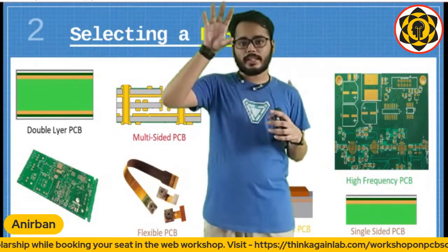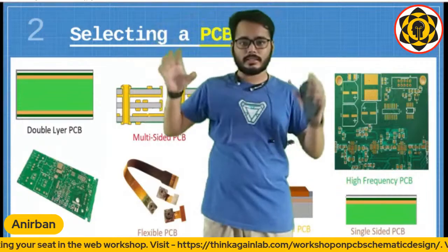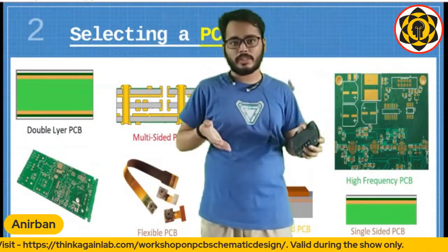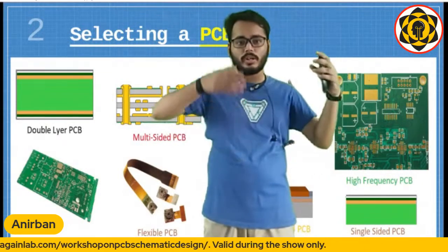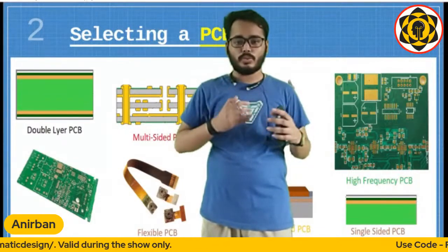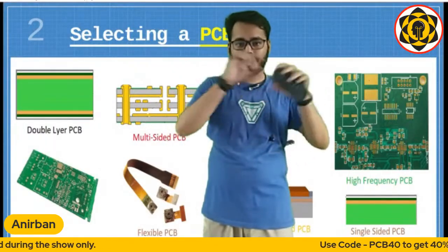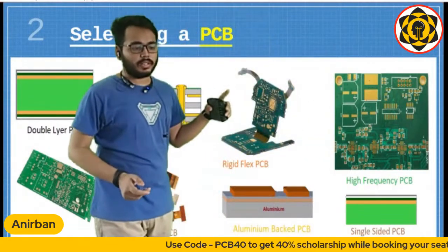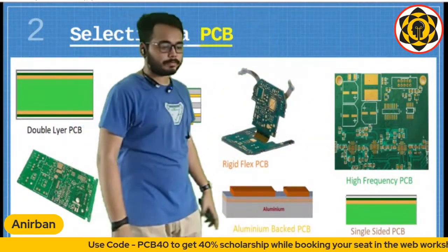So the top layer that has a screen, the webcam, and the Wi-Fi antennas, that is a solid PCB. The bottom layer, obviously your motherboard, is a solid PCB, and then connecting those two are wires or flexible pieces of PCBs. So basically, these two solid pieces are connected by a flexible PCB. That's a very real example of a rigid flexible PCB.